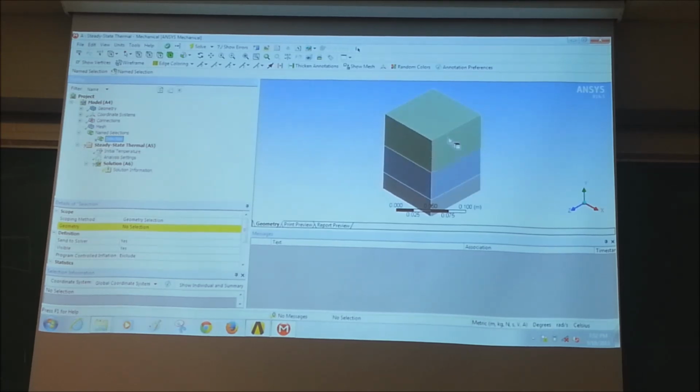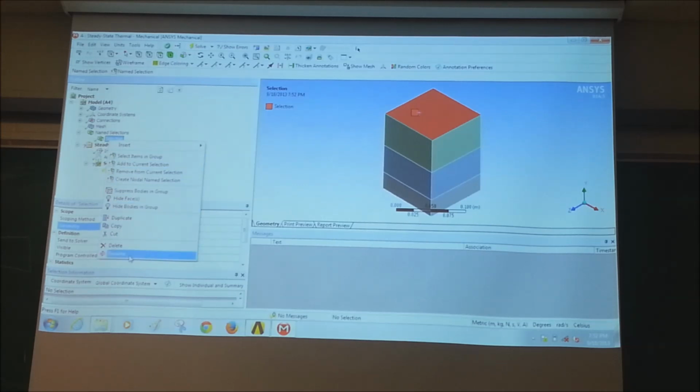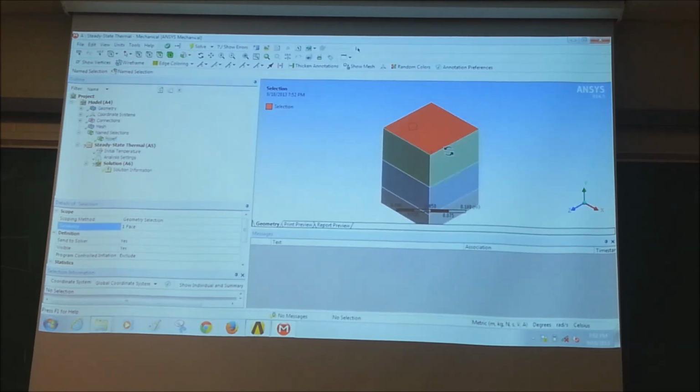This is a surface. So I'll say geometry selection, surface, make sure the surface is selected, and apply. So this is going to be, I will rename this into H coefficient. This is just a surface, right? I'm going to apply. And then if you click this, notice a little red thing comes on, which means I can rotate it. So now I'm at the bottom.